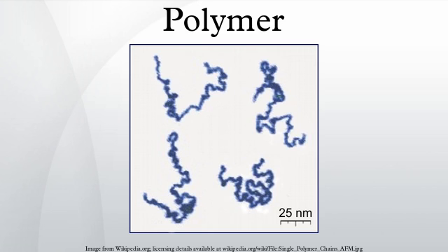Polymer architecture. An important microstructural feature of a polymer is its architecture and shape, which relates to the way branch points lead to a deviation from a simple linear chain. A branched polymer molecule is composed of a main chain with one or more substituent side chains or branches. Types of branched polymers include star polymers, comb polymers, brush polymers, dendronized polymers, ladders, and dendrimers. There exist also two-dimensional polymers which are composed of topologically planar repeat units. A polymer's architecture affects many of its physical properties including, but not limited to, solution viscosity, melt viscosity, solubility in various solvents, glass transition temperature and the size of individual polymer coils in solution. A variety of techniques may be employed for the synthesis of a polymeric material with a range of architectures, for example living polymerization.